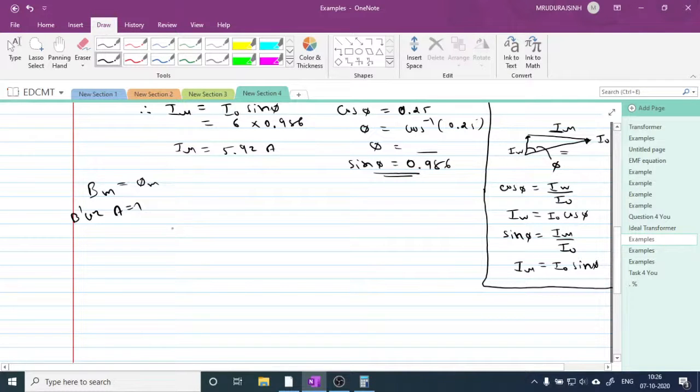So now we have the equation for induced EMF in the transformer's primary. E is equal to 4.44 phi m f into n1. So this phi m f into n1, n1 is the primary number of turns, and f is the frequency, right? Do we have the frequency?